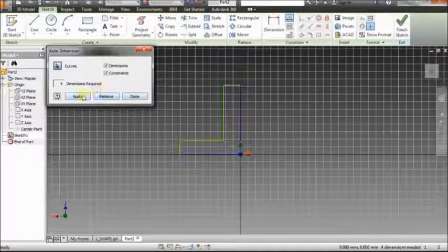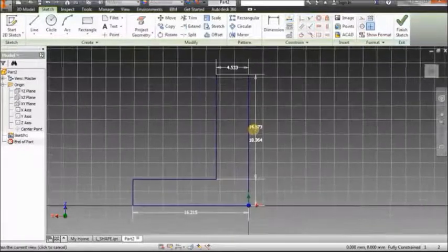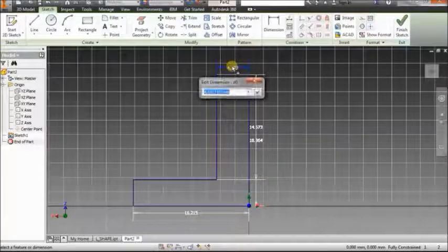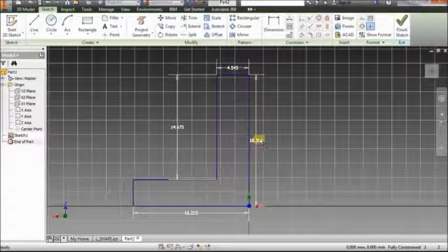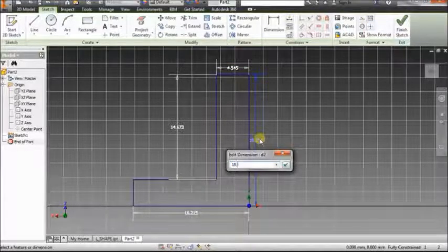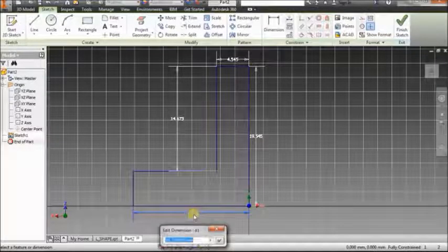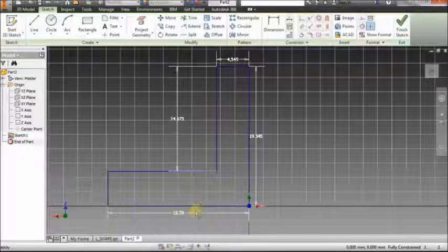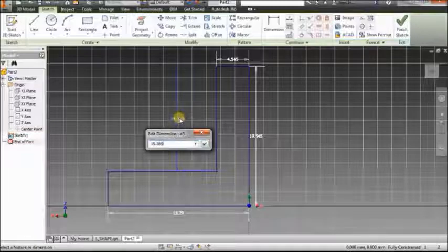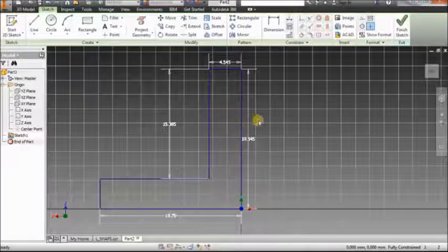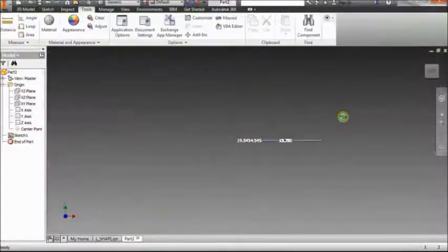Click Automatic Dimension in your constraint bar, select Done, and then we start looking at each of those dimensions and modifying them appropriately. Now notice I'm going in and I'm updating all these dimensions to read as it shows in the practice. So as I move or edit these dimensions, notice how the geometry flexes or changes and updates over time. You'll notice later on as we do this in 3D mode, you can actually see the 3D shape change upon typing in local update, if you remember.